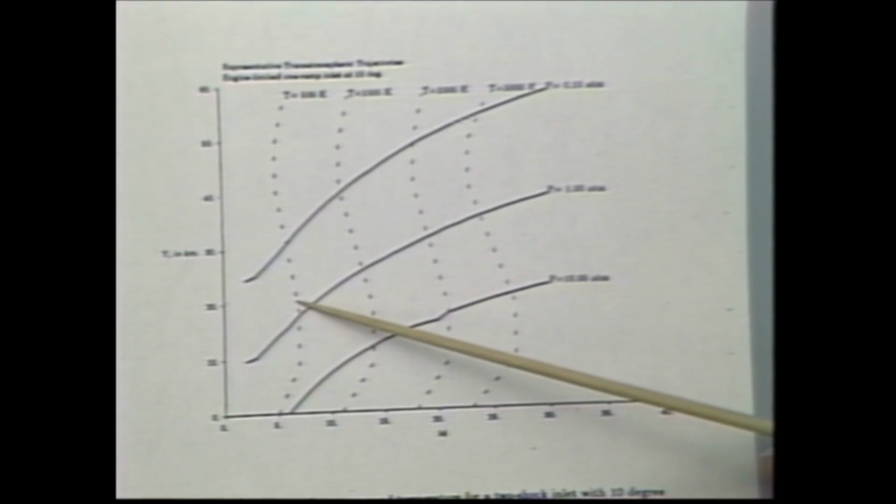This is a plot of altitude versus Mach number. Now remember, I said that we probably would like to be operating with about 1 atmosphere pressure coming into the engine. Well, this line corresponds to what would supply 1 atmosphere pressure. Notice what's happening to the temperature across that shock system. We start out at 500 degrees being delivered to the engine, and we wind up with 3,000 degrees by the time we hit Mach 25.